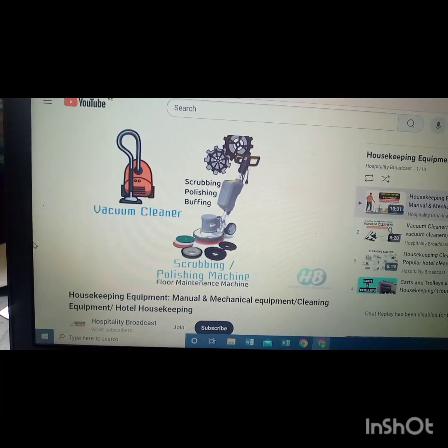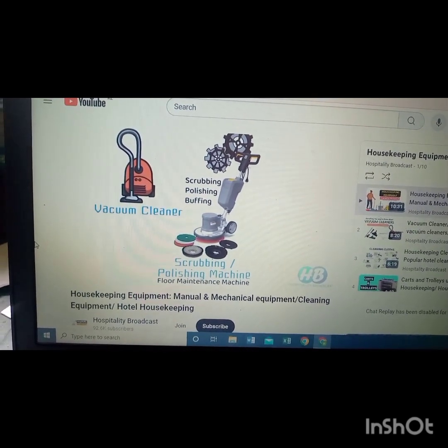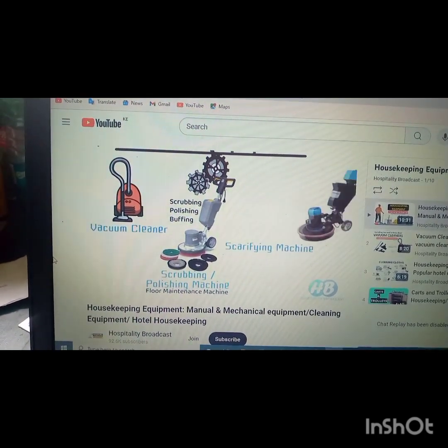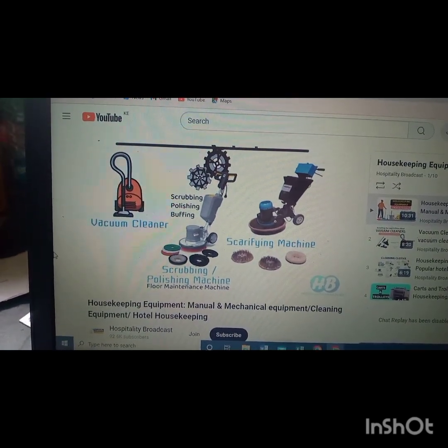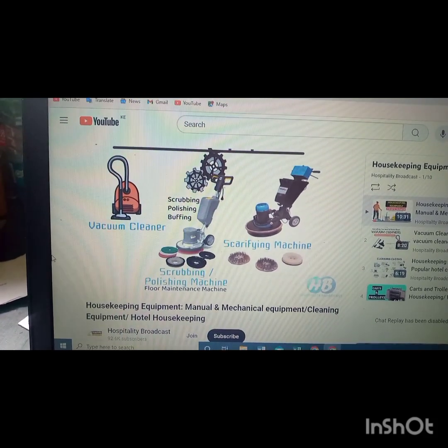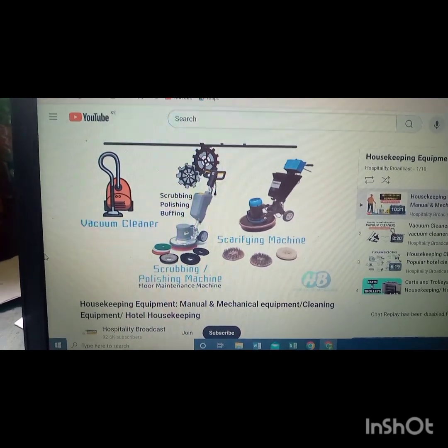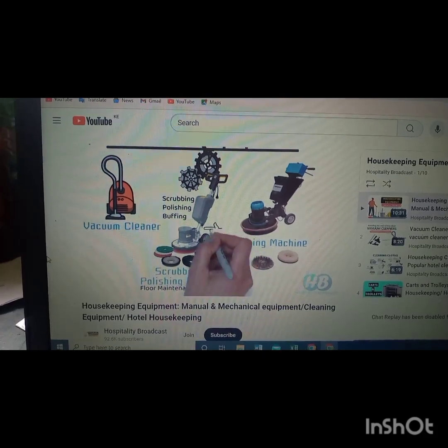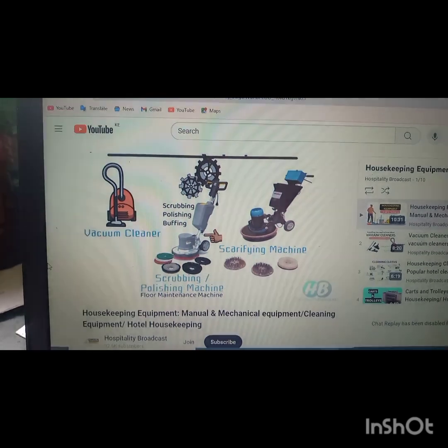When simply scrubbing is not enough, meaning there is a thick layer of grease, mud or wet sawdust, you can go for scarifying machine. In this we use wire brush cutting tool which removes this upper layer by chisel like action. You can also use it to remove upper layer or waxing from the floor. Either you can buy a specialized scarifying machine, or in market we also have more powerful single disc machines which can be used for scarifying with appropriate attachment.